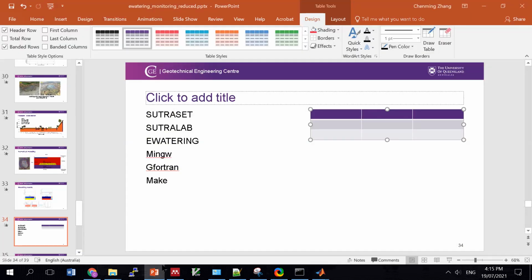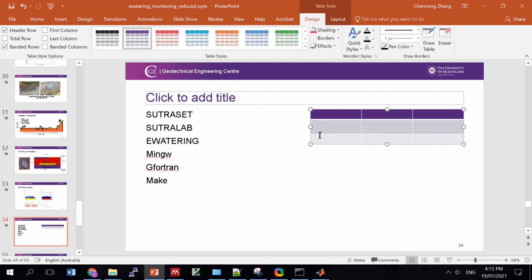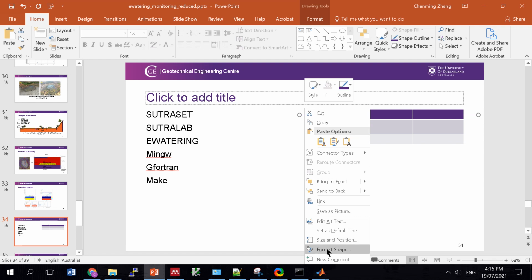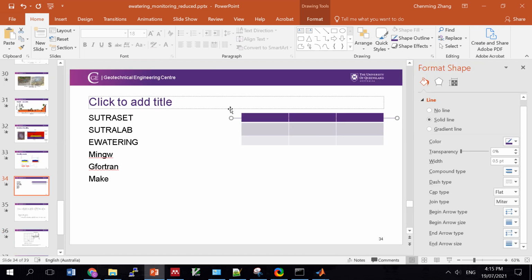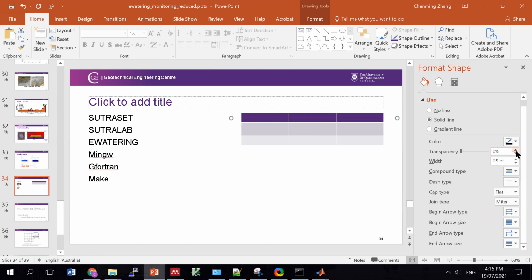So we've already discussed that every single point is called a node. The whole block is called an element. But in SUTRA, there is an extra definition that is called a cell. So the cell basically splits, it has the same number as the number of nodes and assigns the node into a finite volume.